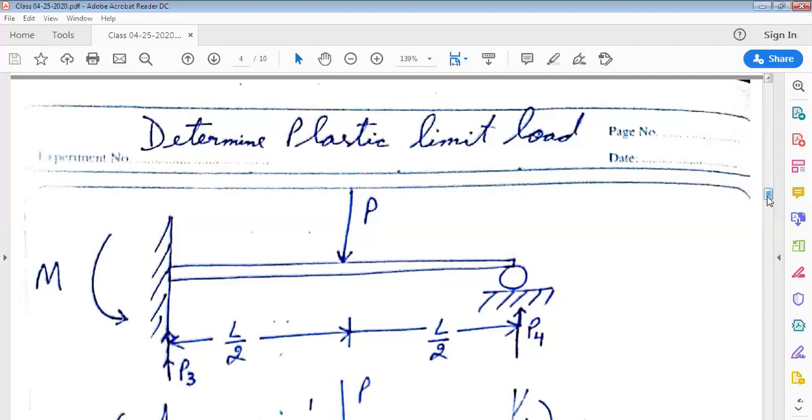Please recall that in displacement method, we assume as if this particular configuration of the structure is made up of two configurations. That means when two configurations are summed up, superimposed, then this particular configuration is arrived at.